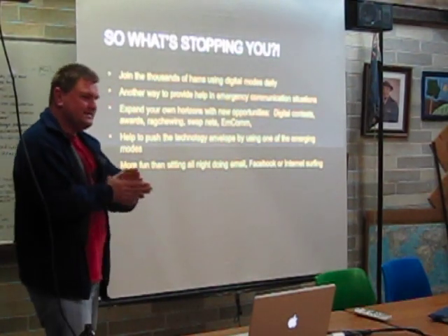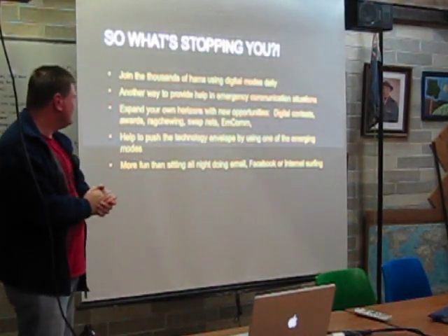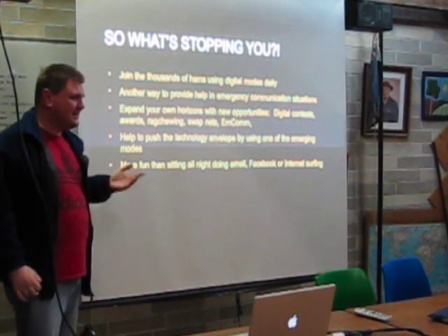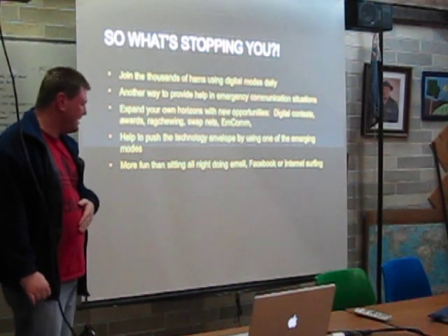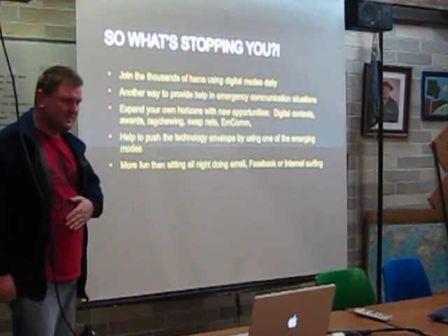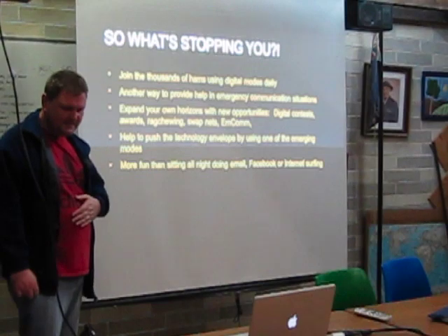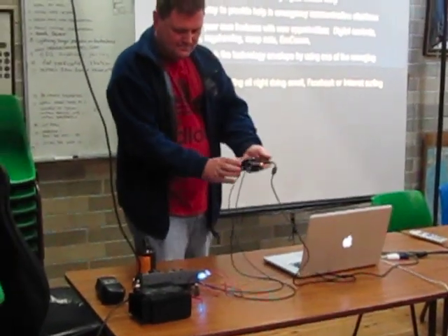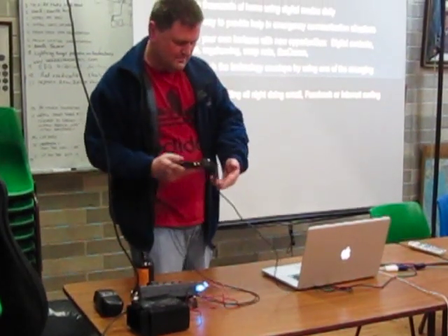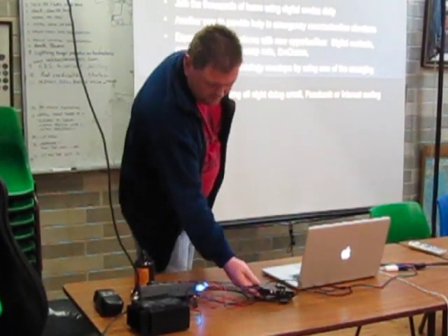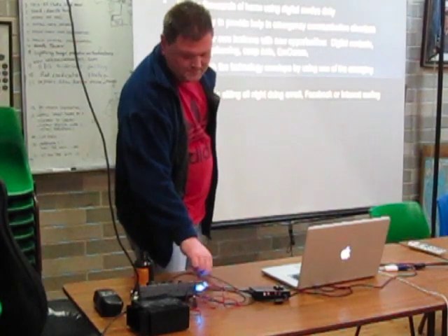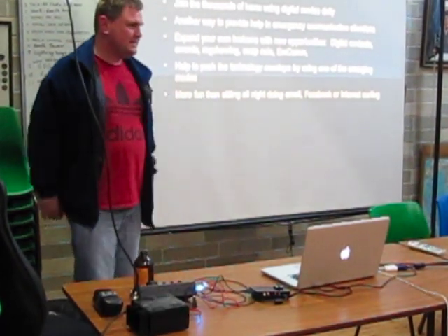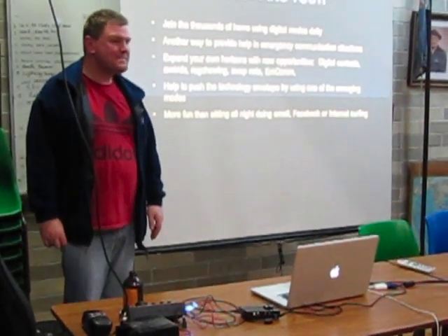So that's basically the end of what I wanted to say tonight. I encourage you to get on the air and give these different modes a go. You can see the equipment's not terribly complicated. In this case, I don't have any special interface at all. It's just a sound card, plugs straight into the radio, plugs into the computer. I use the box on the radio to turn the transmitter on and off, so I don't have a separate keying line. And yeah, you can go on and play.